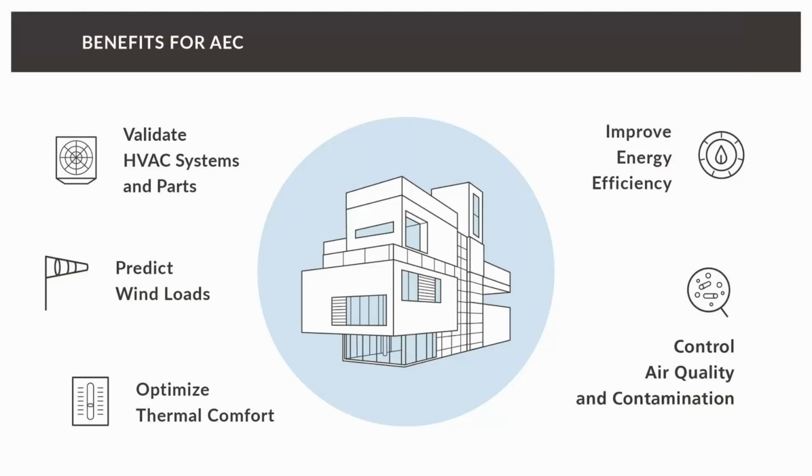Another application which is very much related to that is improving the overall energy efficiency. This is very important, for example, when it comes to natural ventilation, which is not so important for industrial applications, but for residential ones. There you can use CFD, for example, to understand flow patterns, to understand how your building is interacting with its environment, and to see if and how a natural ventilation strategy could be leveraged.